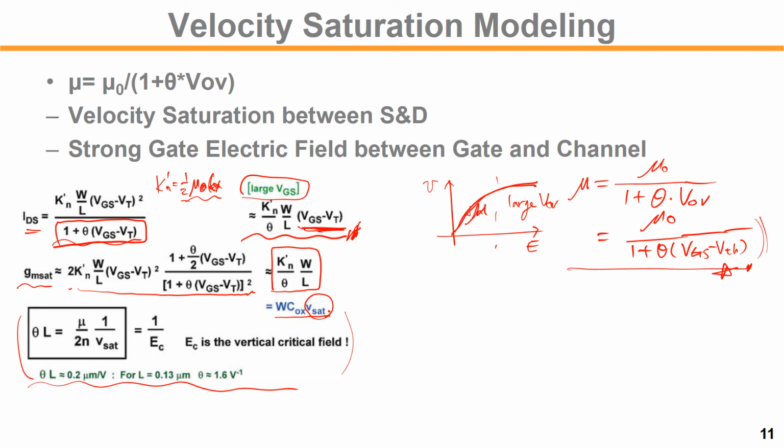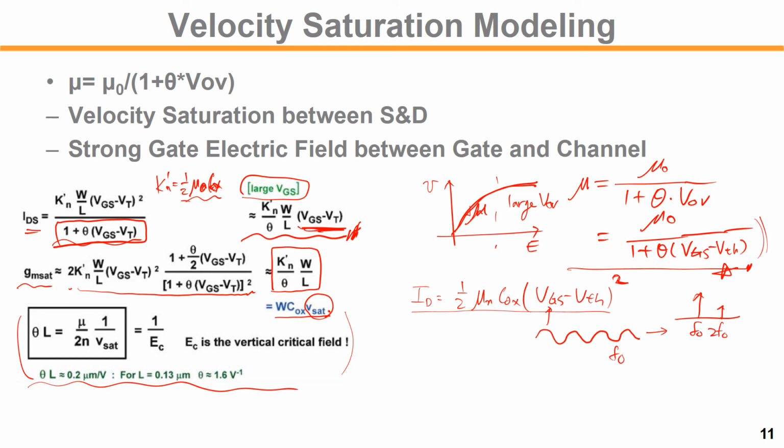For example, for conventional device modeling, ID equals the square law equation. When VGS is modulated with a pure tone, since this is a second order square law device, the distortion will be only the first fundamental F0 tone plus the second order tone at 2F0.